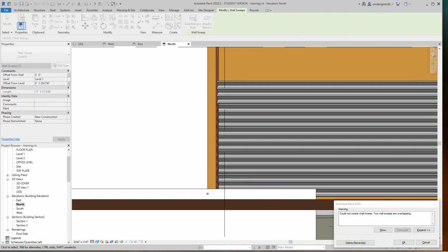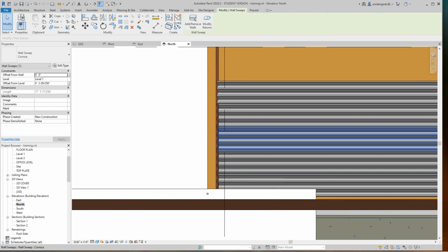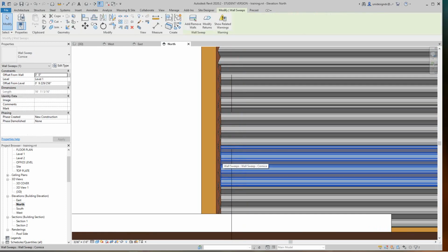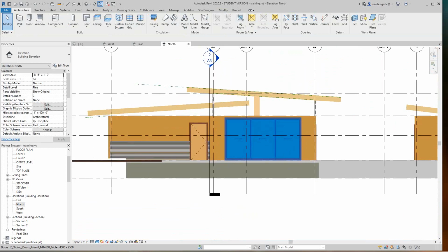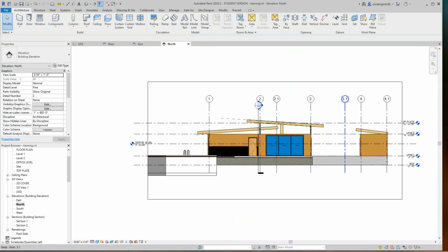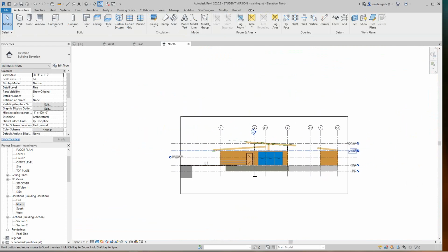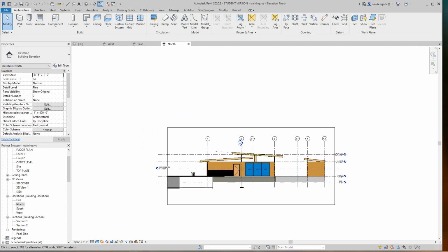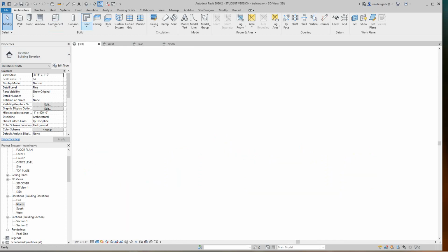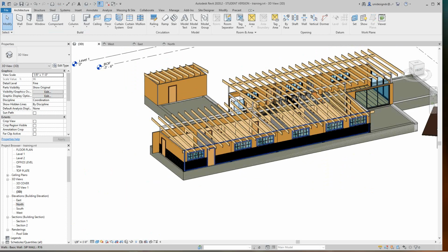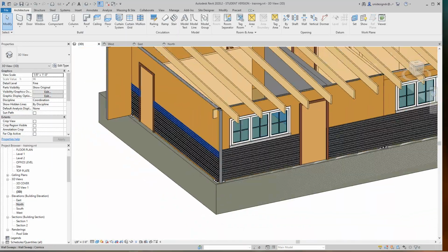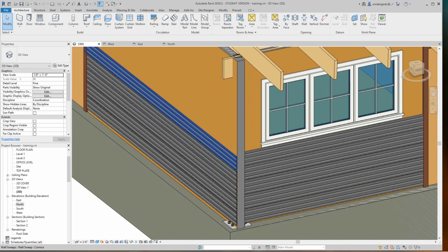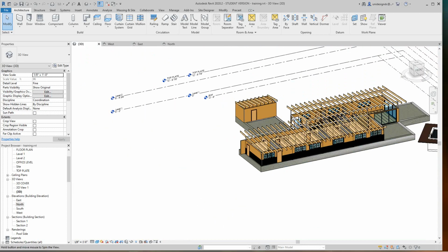And we can also, to get these situations here, we can pull stuff back and void with the dots and everything. So there's that side. Let's take this around. Oop, the 3D view. So there's our corrugated aluminum panels. Oh yeah, and by the way, the material I'm using is aluminum. So there's that side.